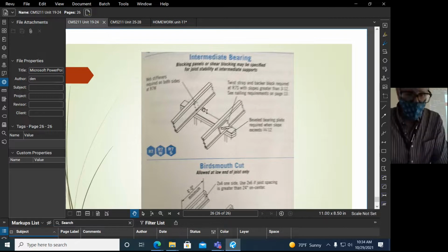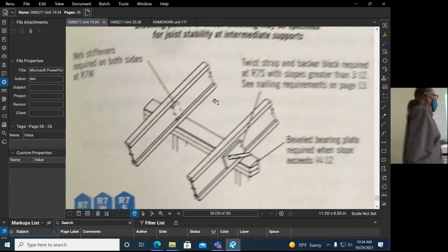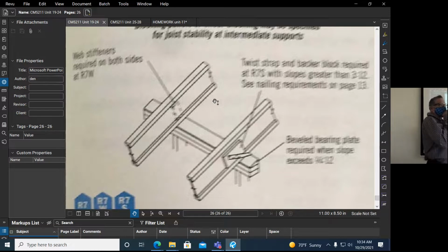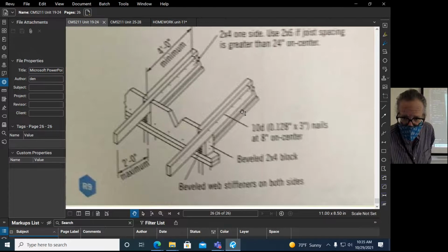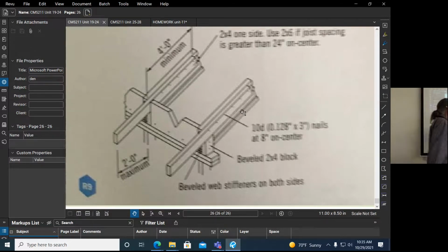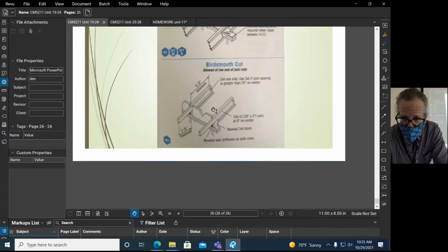So we have to be concerned with truss choice. These elements, like I said, this plywood web is really sensitive. Sorry for the blurriness of this thing. There's a better picture in the book. So this is like an LVL member, laminated veneer lumber, top and bottom. So this has to be trimmed there. The bird's mouth can only come out of that part. It can't come out of the web at all. Okay, and then if you do have to do that, then you have to reinforce it next to it with fully reinforced 2x4s.